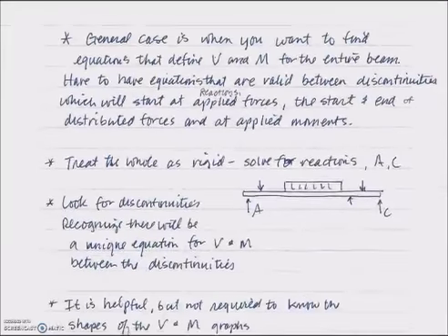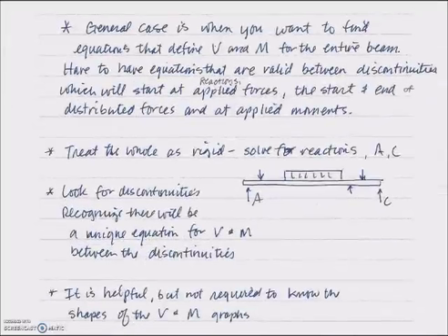What we're going to do today is do the general case, or understand the general case, when you want to find the equations that define shear and moment for the entire beam. Here, there are equations that are going to be valid between discontinuities, and a discontinuity will happen every time there's an applied force or a reaction.